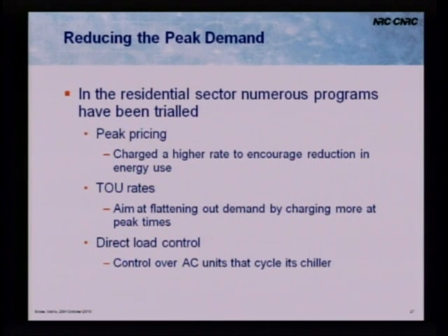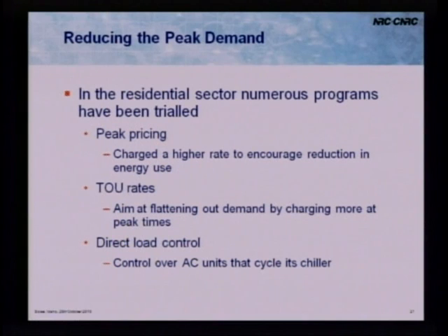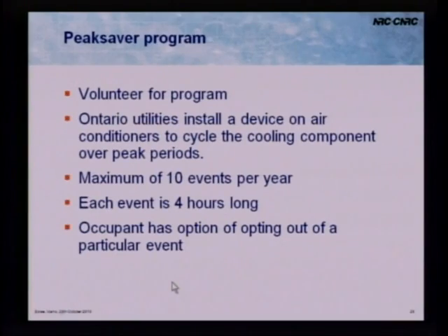So to reduce the peak demand in the residential sector, there's several different trials out there. The first of these is peak pricing, so charging consumers a peak price at peak times, and this will encourage them to use less energy at this point in time. Time of use rates try to flatten out the demand over the course of the day and aren't really aimed at peak periods. The Peak Saver program in Ontario uses a direct load control method